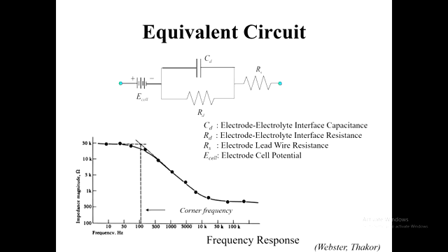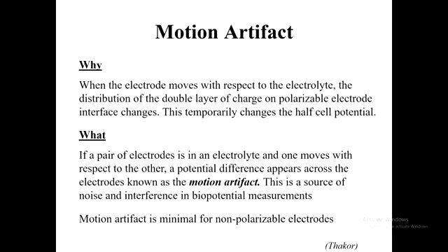Okay, we've got a few more minutes before the notional mid-break. What I did want to talk to you a little bit about was the heavy-duty information overload that we've got here, talking about motion artifact, which is one of the things that bedevils us. Like I said before, that's largely due to movement between the skin and the electrode, or the electrode foam layer within its housing, that will create a change in impedance in the pathway.